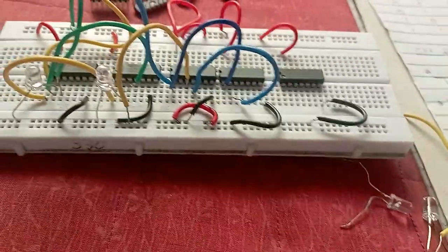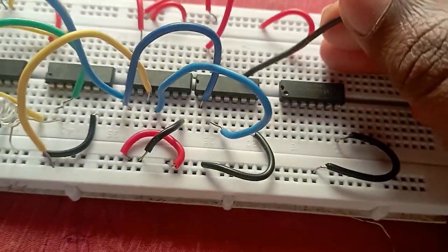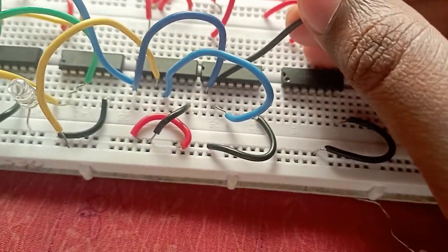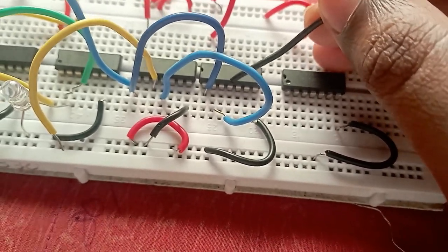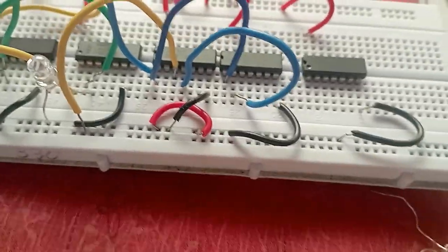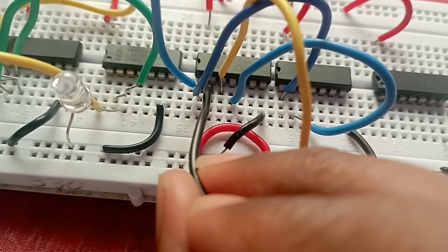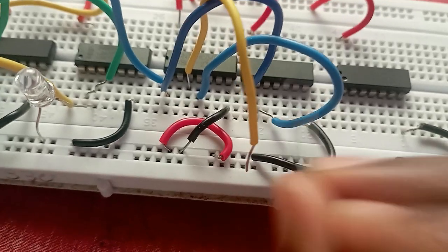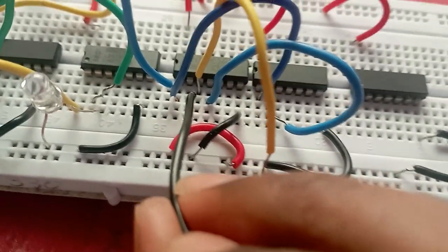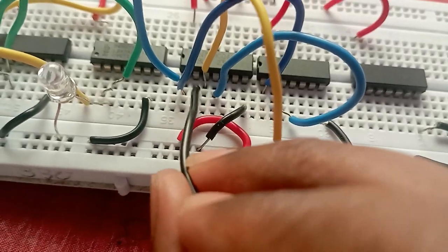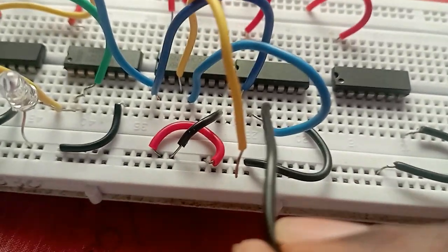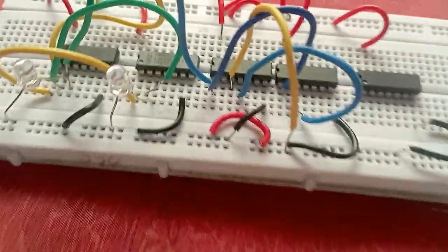We are going to use another AND gate. So I am going to use the AND gate of 4th pin and 5th pin, and the output is going to be at the 6th pin. You can use any AND gate. So this is 1, 2, 3, 4. This pin is going to get A bar and this pin is going to get B. So A bar we are going to get at the second pin, which is going to be connected at the 4th pin, and we want B. So B is at the 3rd pin, which is going to be connected at the 5th pin. So this connection has to be made. I am going to connect them.